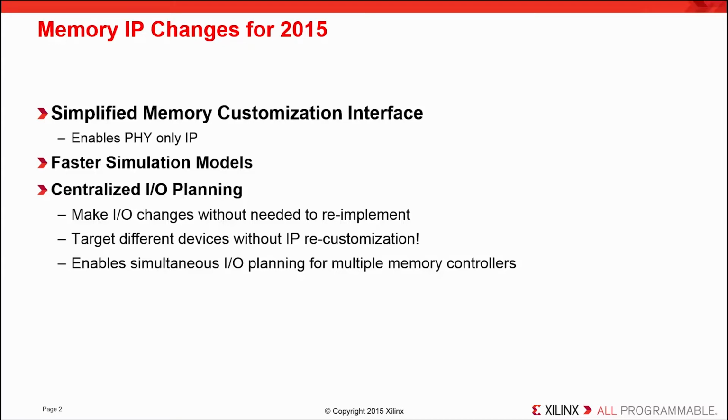This gives you some specific advantages. It allows you to target different devices with the IP without re-customizing the IP, and it enables simultaneous I/O planning for multiple memory controllers. This also makes the behavior consistent with other IP in the Xilinx catalog.